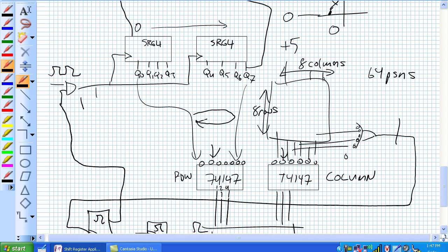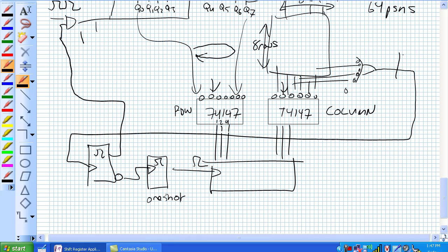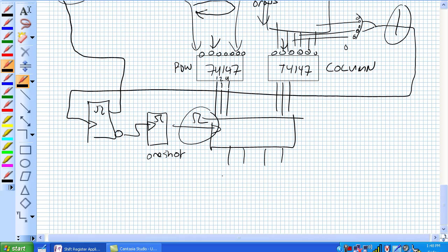So basically, row is constantly getting 0, but like I said earlier, your fat finger presses this thing down. Finally, the column's got a 0. This thing says, hey, we got something, inhibits the clock, enables the clock on the shift register. Excuse me, in this particular case, it's going to be a parallel in register. It comes in, and there it is.